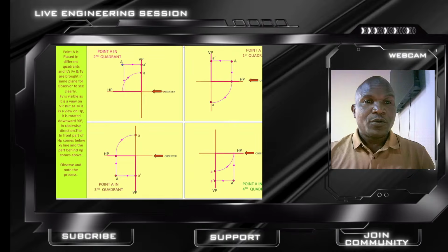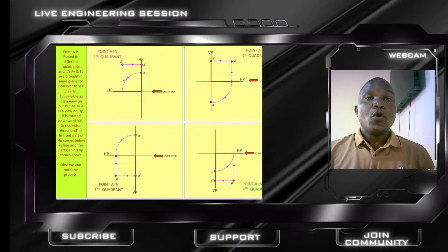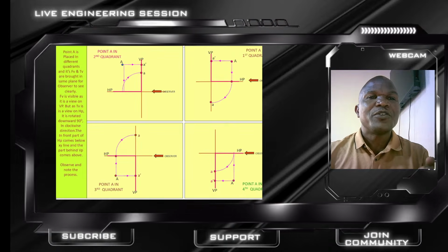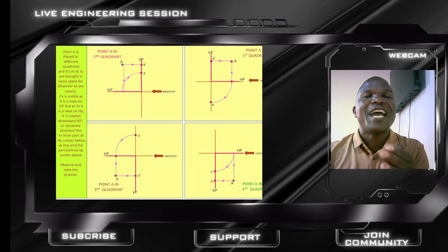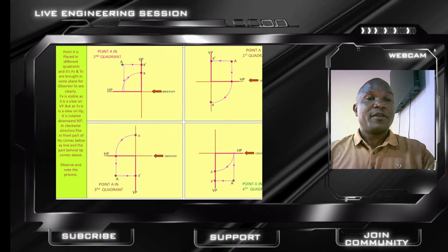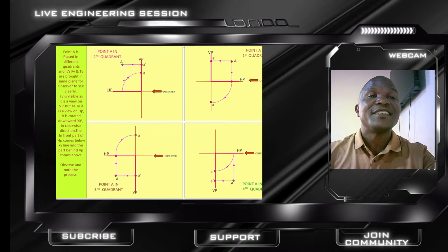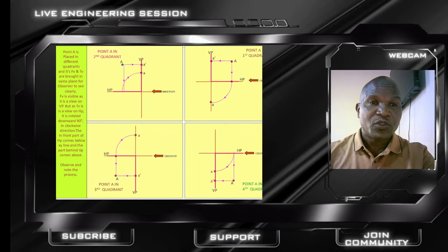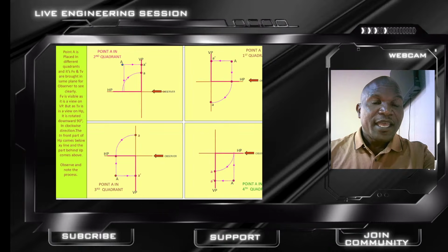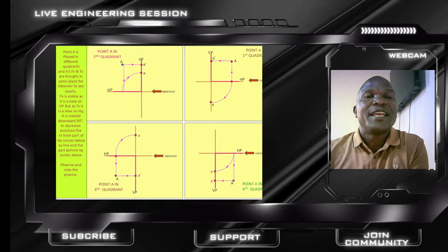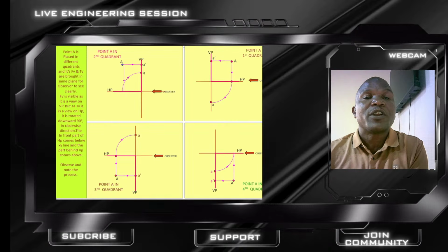So what do we do? We rotate, repeat again, we rotate the horizontal plane HP downwards by 90 degrees. That's why the front view stays where it is. Pay attention to the front view in the slide. And the top view moves below the XY line. This is the reason behind the standard layout, not just a rule to memorize.